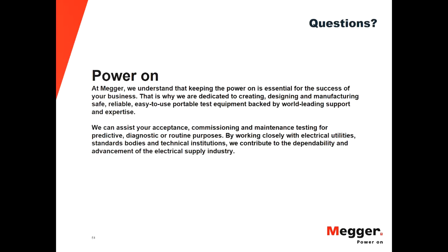However, the rate-adjusted method will come up with higher accuracy results, and it can also be used for tests longer than 1 hour. The difficulty is that for the rate-adjusted method you need to consider the aging factor of the battery. You can assume 80% is the aging factor of the battery.